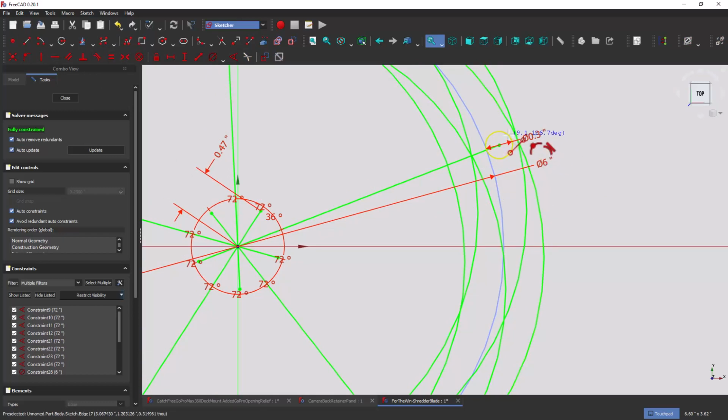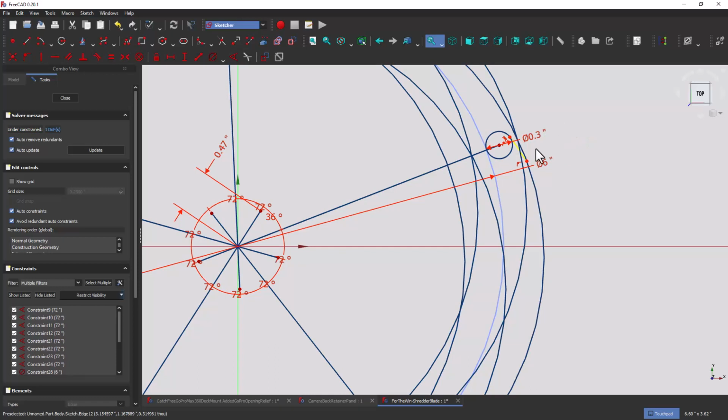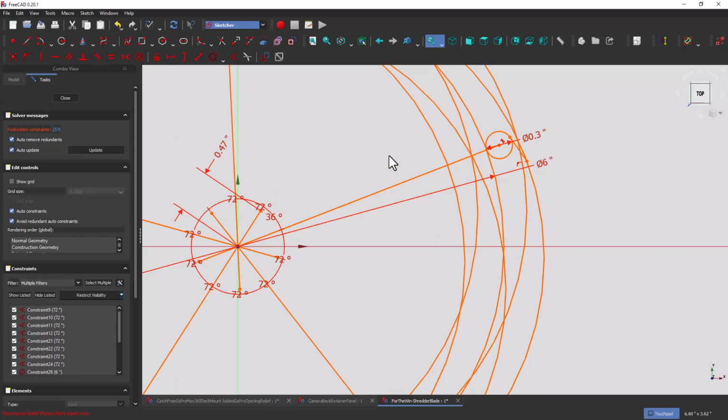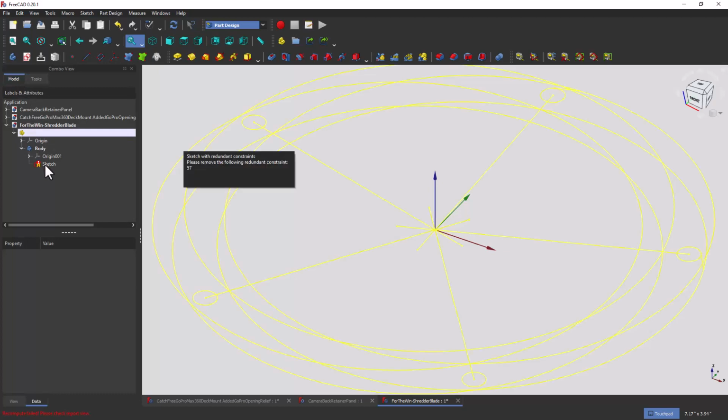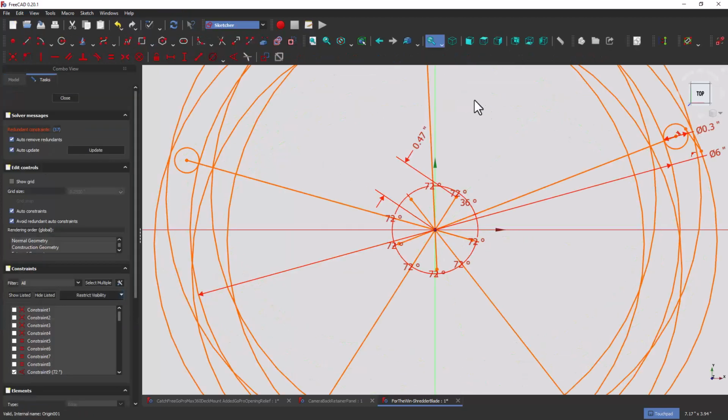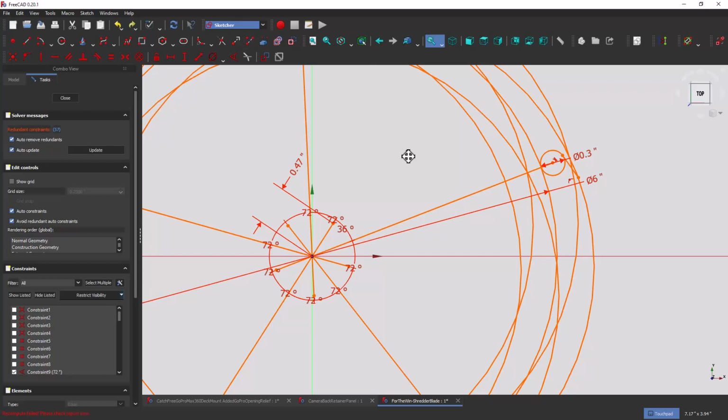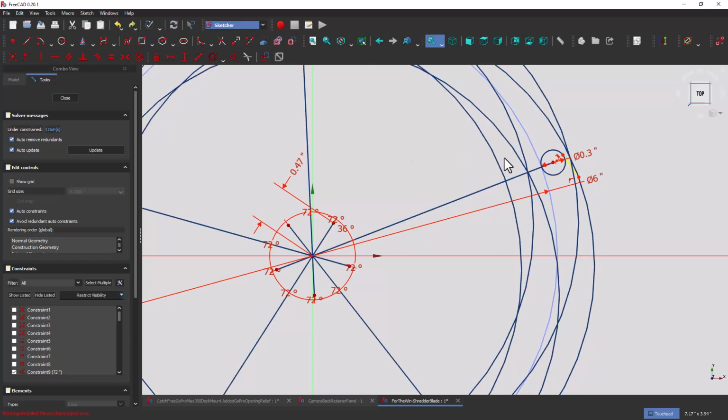Once you get a handle of the geometries on there, okay, so I'm going to take my little extra line and make it tangent on there. Ooh, doesn't like that. Sometimes when it does that, I hit escape, I have to come back and edit. All right, Control Z. Let's undo that constraint. Let's do it again. I might have picked the wrong things that have been selected here. That. Okay, let's try the tangent. It doesn't like that.